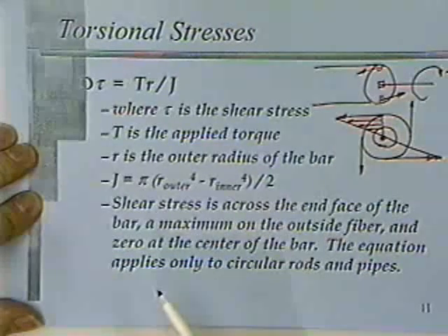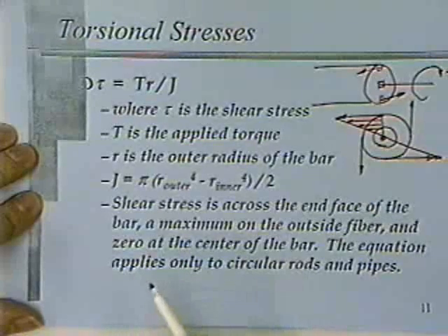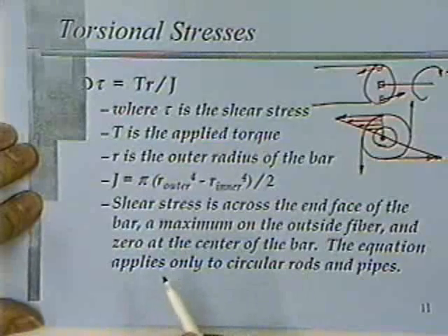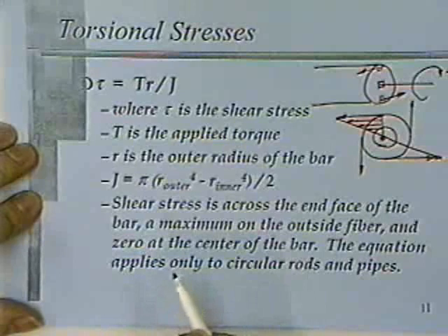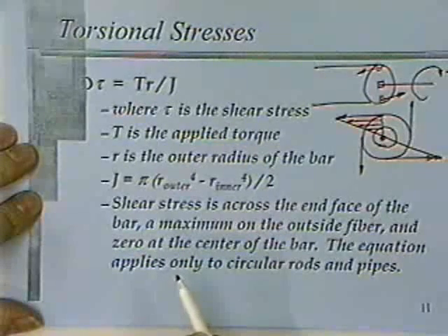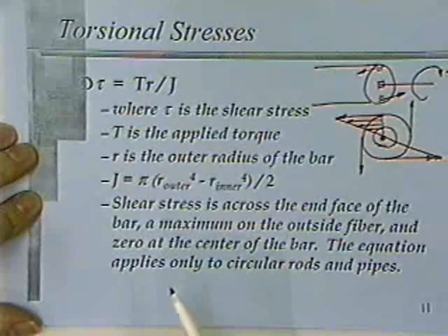If it's going in an aircraft, or if it's going to the moon, then they probably will take the center out because they're not so much worried about the recovery of steel. They're worried about having to haul that pound or 2 pounds around with them for the rest of their life. Big old shafts, like a drive shaft in a car, will almost always be hollow because they don't want to waste that amount of steel.